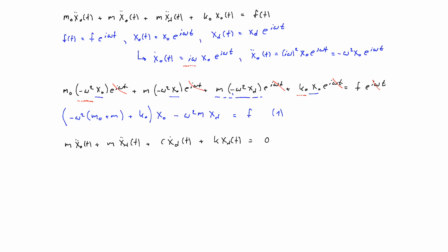So I believe that for this second equation of motion in the time domain, we can simply write the frequency version directly, because we collect everything with x0, that's the first term, and we can write it as minus omega squared m x0, because we know acceleration is simply a factor minus omega squared.